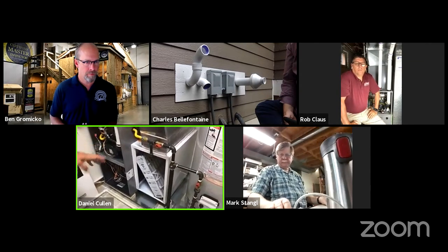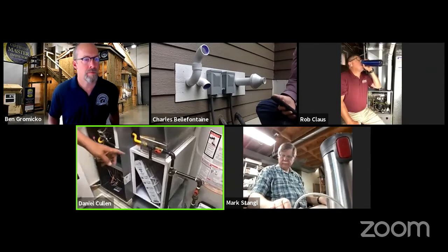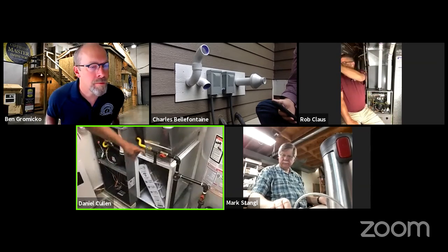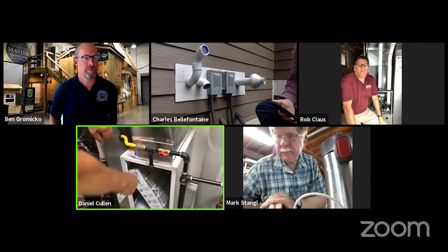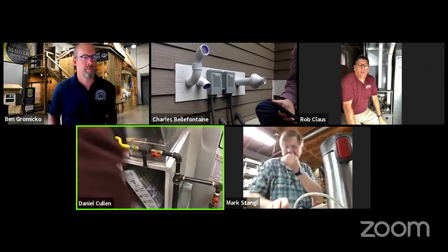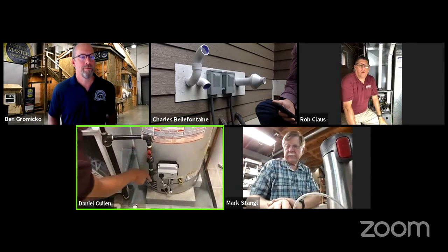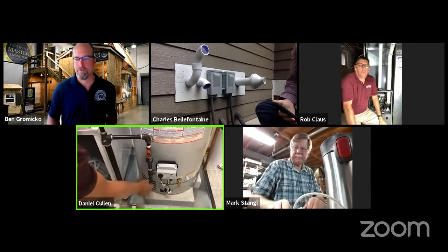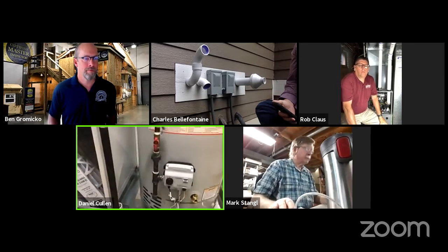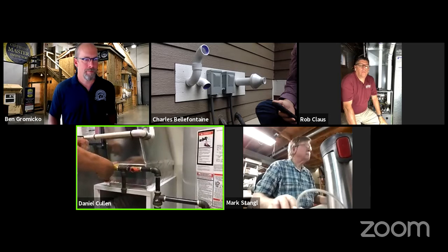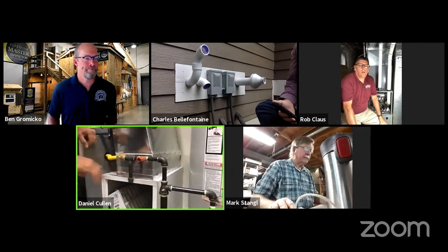There's a couple things here that my contractor did that eventually I'm going to have to change, and the guys who are really sharp have already seen it. One is this is not a proper drip leg, right? You have to have a change of direction. This is a proper drip leg here, right? Because the gas is coming down, and then particles go straight down into the extension, into the nipple, before they come into the gas valve. Here we have our gas flowing this way, and there's really nothing that's going to make the particles or moisture drop down here. That's incorrect.